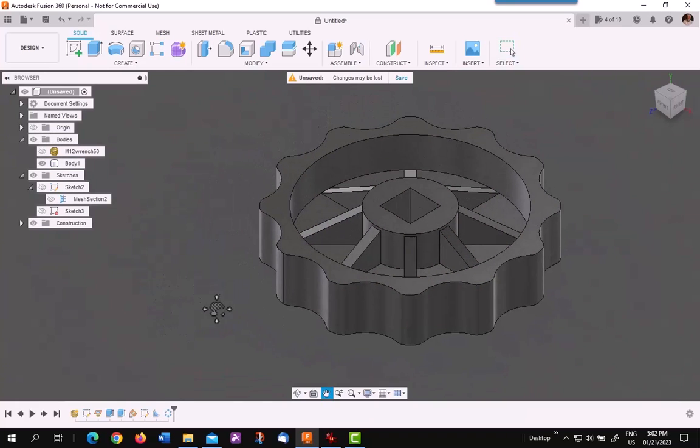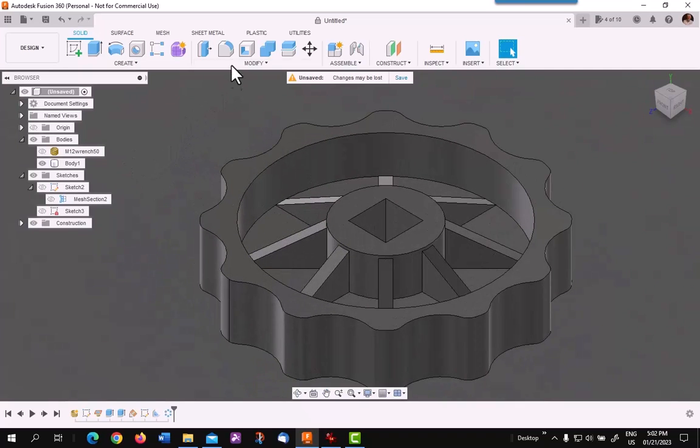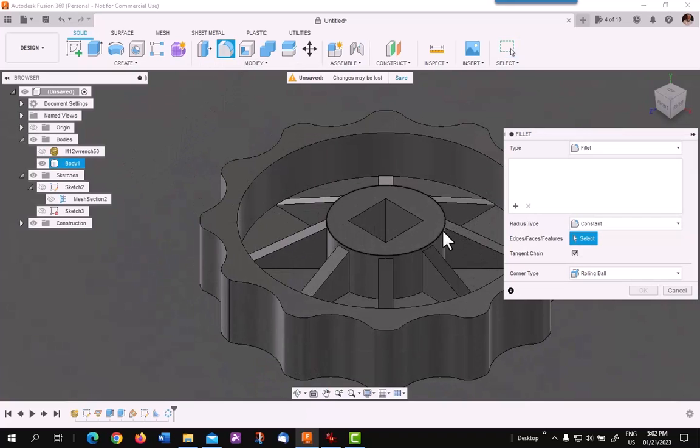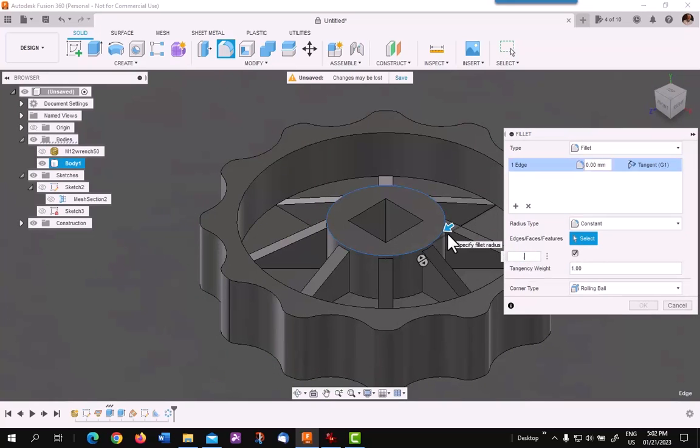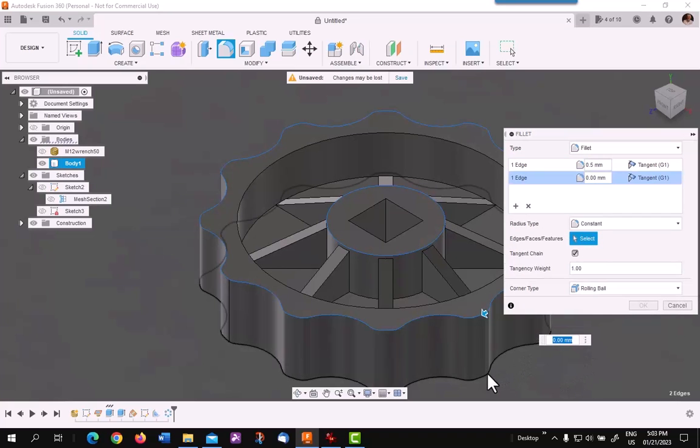As you can see, we've now almost completed our body. Let's add the finishing touches. The last step I want to do is pretty it up a little bit. I'll use a fillet on this top edge of ½ millimeter. And I'm going to also, in the same command, pick these 2 edges. Notice how clean they are from our process, and I'm going to make these 1 millimeter.